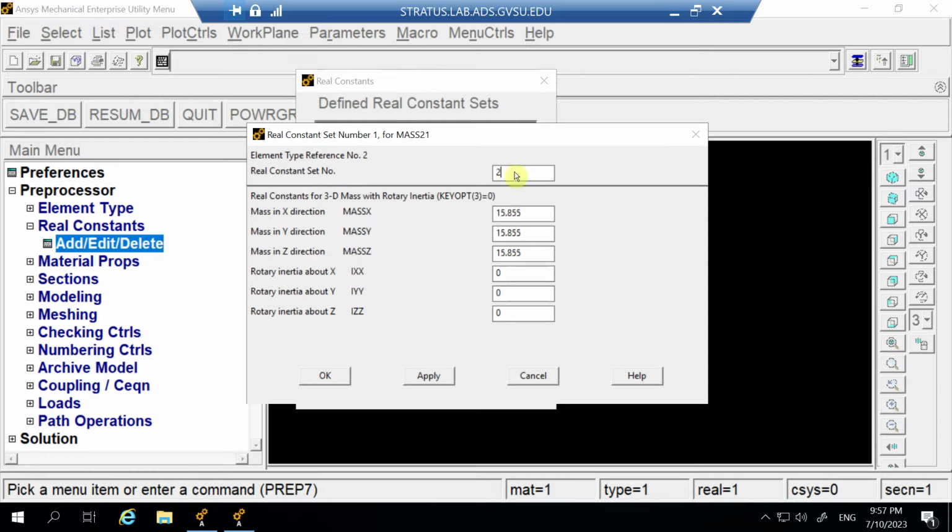Now the second gear. You see that mass was converted to kilograms. You can use ANSYS as a calculator here. The other mass is the gear that weighs 55 pounds, so 0.453 times 55. I need to do the same here. You can copy and paste it.